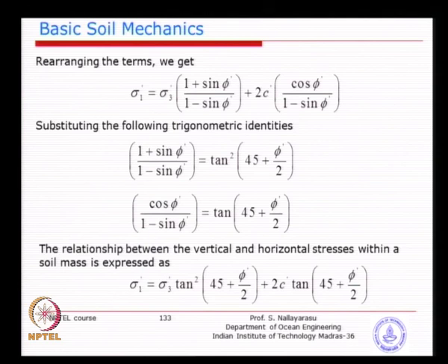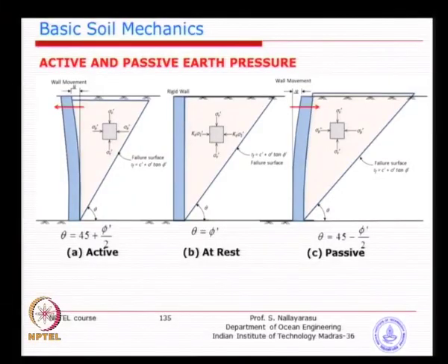because remember when we are deriving a foundation capacity, when you apply a loading to a foundation, it transfers the loading vertically down, and it puts pressure on the soil and the sides, and that pushes horizontal pressure actively. And what happens to the soil, the state of stress from the rest case, it is going to get compressed. And if the soil stresses exceed, the soil will come outside. So, that is basically the idea. Whether you apply vertical stress or the horizontal stress, we need to know the relationship. So, we will just go to 3 cases in this particular earth pressure theory.